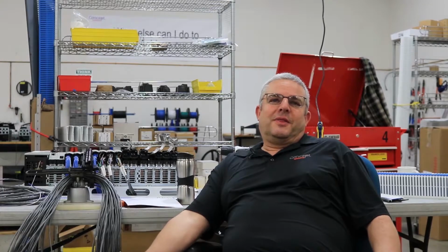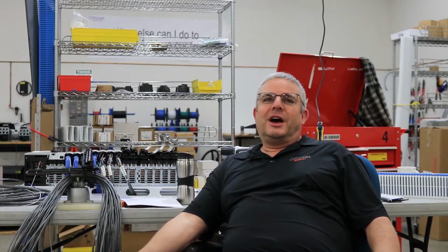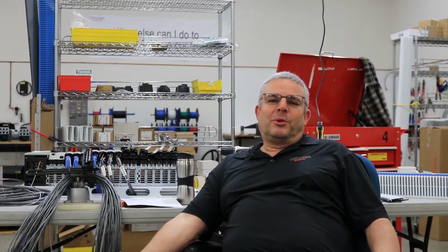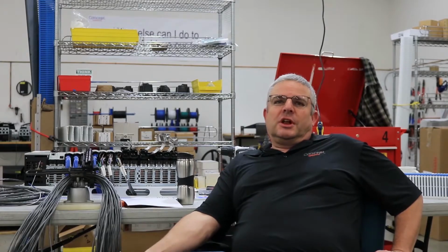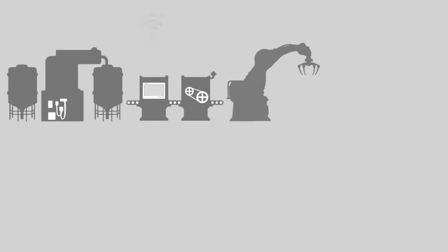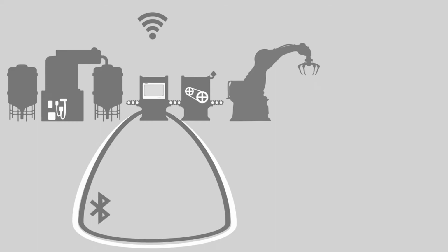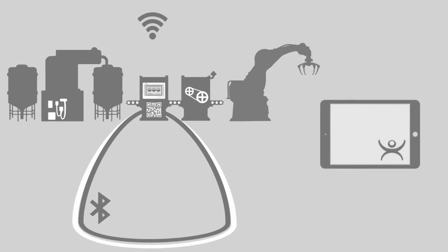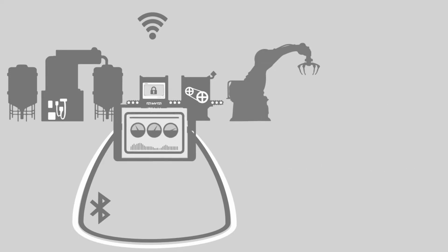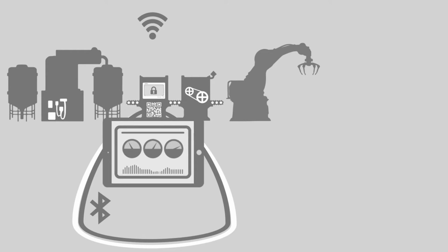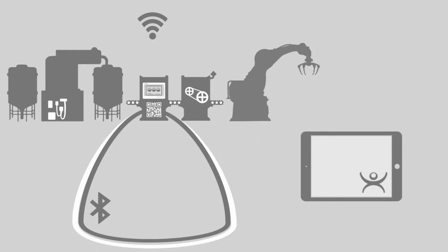So I always fear that D-Day, right? The day your computer dies. So this is a really good way of being prepared for that. So one customer where we put it in, what this does is it now allows for mobile clients. So you've got thin clients out on the floor, which is basically just an HMI like you would normally have. And then there's mobile clients where it pushes it out to an iPad. And so it allows the operator, as he's making adjustments, he carries it with him, climbs up inside the machine, then he can look at it, make his changes, go back down for, say, adjusting glue rolls or glue gaps or some of those finer adjustments.